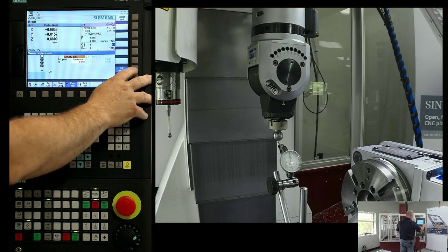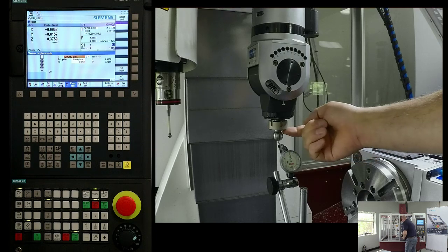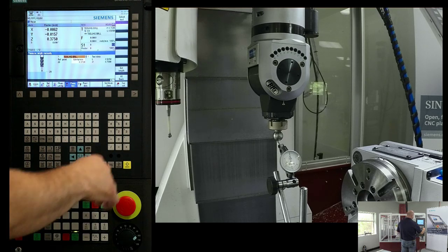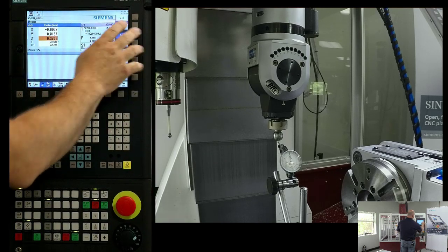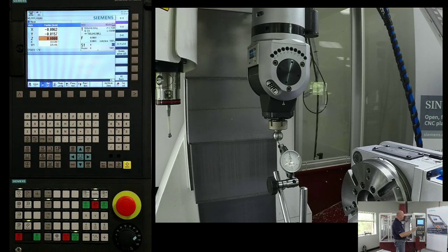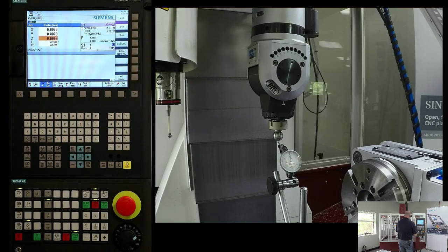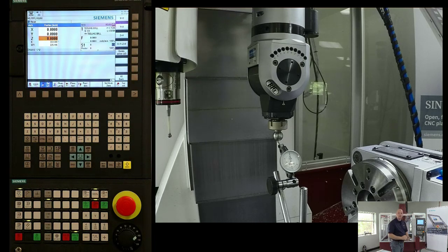So I hit set length, and the system then calculates a value of basically a half an inch. If I was to do a quick measurement from this face to the center of that sphere, I would buy that that's a half an inch. So now it knows the tool offset. Last step in this check is to reset your Z-axis coordinate system to 0, because I want to be able to come back and repeat back to this point, and I want to set my X and Y 0, 0. Okay, so now it's time to see if everything we did is going to function.